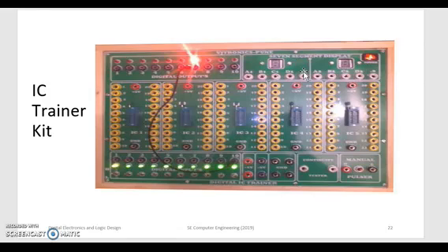Okay, and when you are making the circuit, when you are joining the cables or placing the ICs, the power should be turned off. Once you are done with all connections and placing the ICs, then you have to power on, give the input, and check whether it is generating the correct output or not.